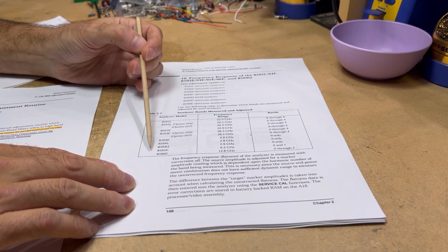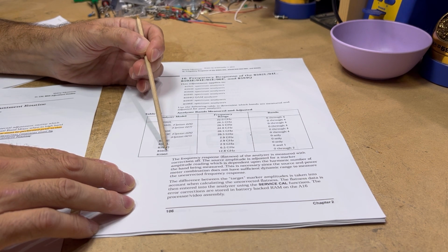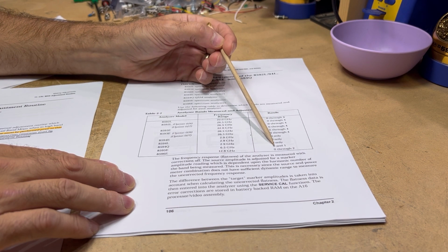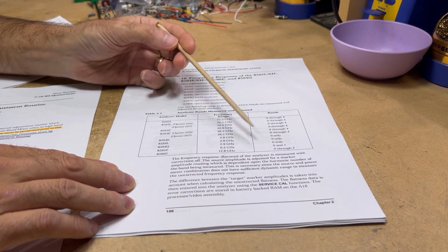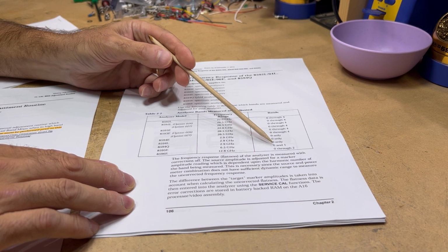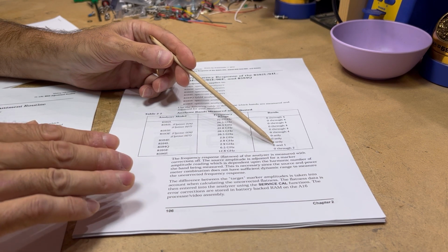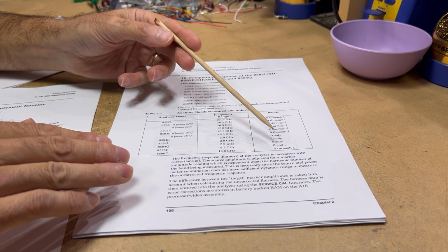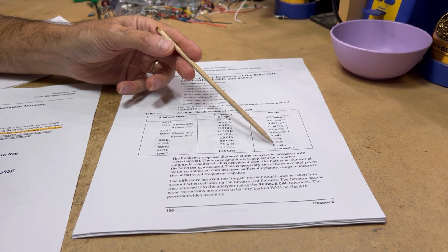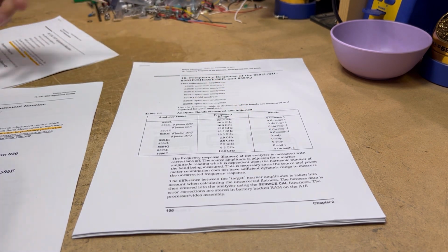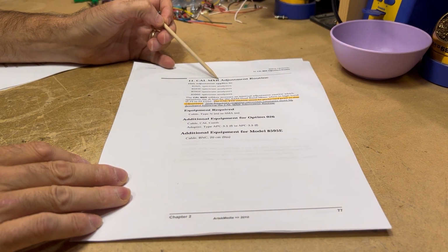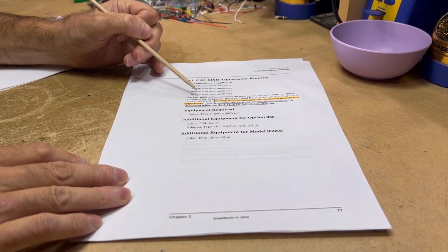So like I mentioned earlier, we're dealing with an 8595E spectrum analyzer, which has two bands, and I'm going to do the low band, which is band 0, and that's going to go from the bottom to 2.9 gigahertz. And then after we get frequency correction constants for band 0, I'm going to go back and perform the cal mixer adjustment routine,